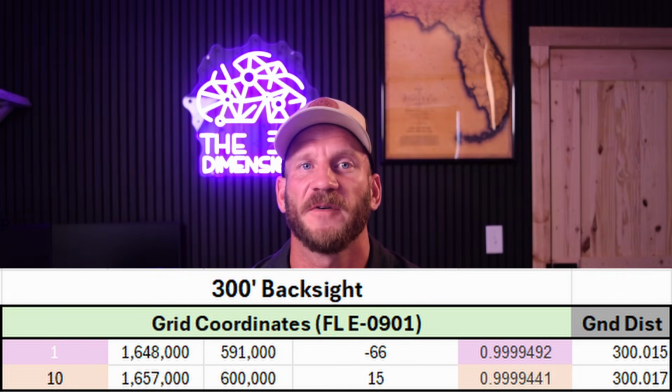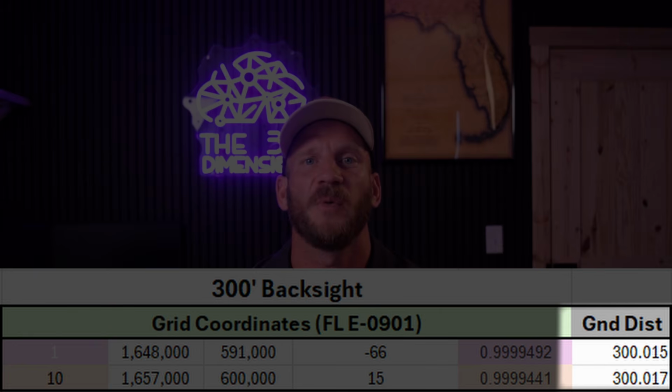the CSF. And this does not mean that if we were to set up on the edge of the network and backsight a point 300 feet away, we would see 1 centimeter of error in the backsight distance. This error is relative, so at that 300 feet, if we measured a perfect ground distance with our total station between the shifted ground points, we would be out by a fraction of a millimeter.